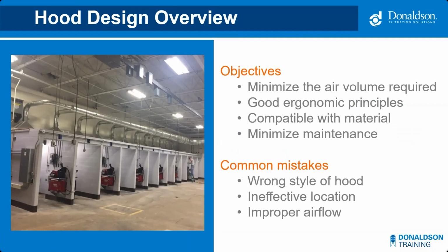It should be designed with good ergonomic principles in mind. It should be compatible with the material flowing through the work area, and it should be designed to minimize maintenance and other activities that may disrupt the process. When it comes to assessing an existing system, a few common mistakes I see are the wrong style of hood is being used, the hood is not being located in an effective position, or you have inadequate airflow to the hood.